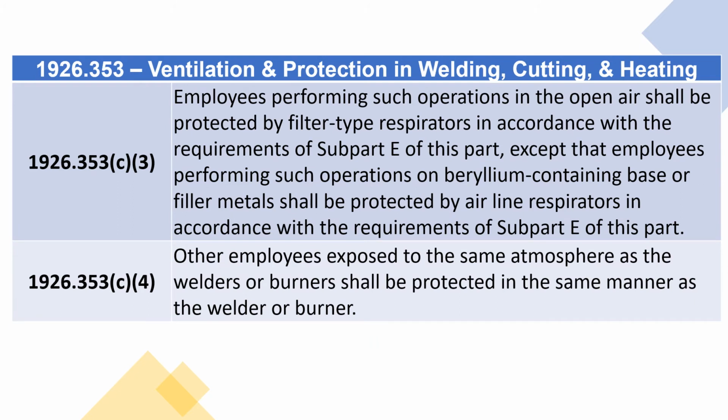C.3. Employees performing such operations in the open air shall be protected by filter-type respirators in accordance with the requirements of Subpart E of this part, except that employees performing such operations on beryllium-containing base or filler metals shall be protected by airline respirators in accordance with the requirements of Subpart E of this part. C.4. Other employees exposed to the same atmosphere as the welders or burners shall be protected in the same manner as the welder or burner.